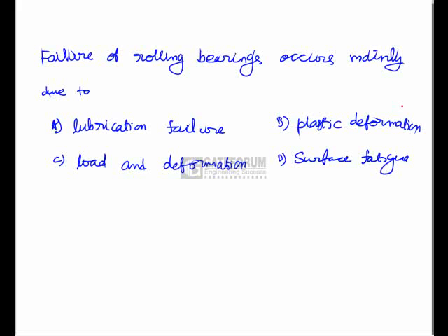Failure of rolling bearings occurs mainly due to, here: lubrication failure, plastic deformation, load and deformation, and surface fatigue. Generally, bearings are subjected to variable loads at the surface level, so they fail due to surface fatigue.